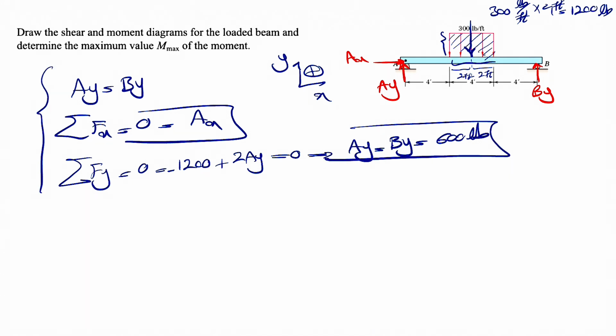And we know that in these kinds of 2D questions, we have 3 equations in total: Fx, Fy, and the moment equation. If we use that moment equation, and let's call this point C, and do the sum of all moments about point C equals 0, we're going to reach the conclusion that AY is equal to BY, which we already figured out by the symmetry of this beam.